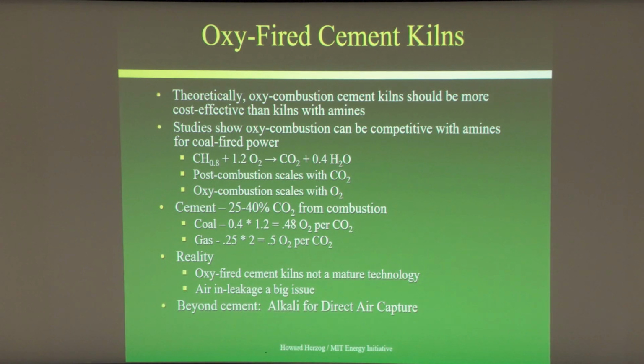But oxy-fired cement kilns are not a mature technology. Once again, air leakage can be a big issue, especially in a kiln, even more so than a boiler. So these issues need to be resolved. When we talk about direct air capture, there's talk of oxy-firing kilns.